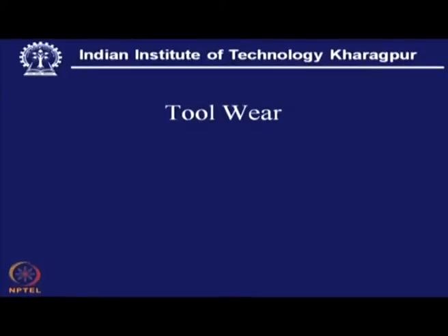However, what is important here, the major role played by TiN, is how to combat tool wear. It is actually holding the tool wear, reducing the rate of tool wear, and that is the greatest contribution of titanium nitride: holding the geometry of the tool, holding the capability of the tool even at that high speed, where the uncoated tool will reveal its weakness and exhaust its life so quickly.